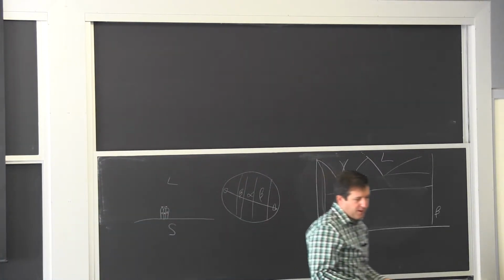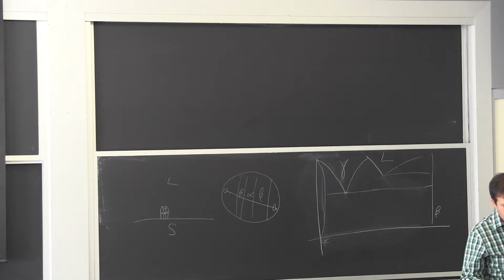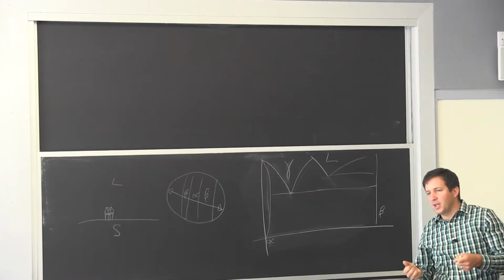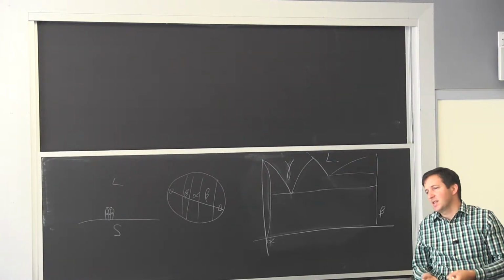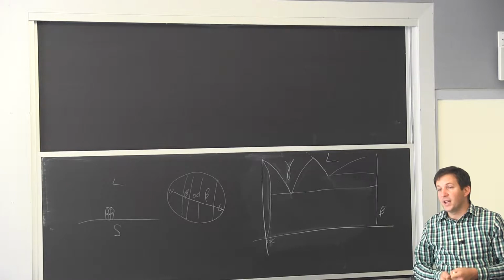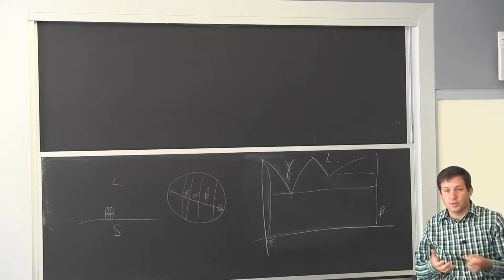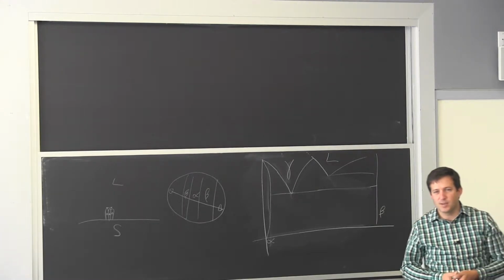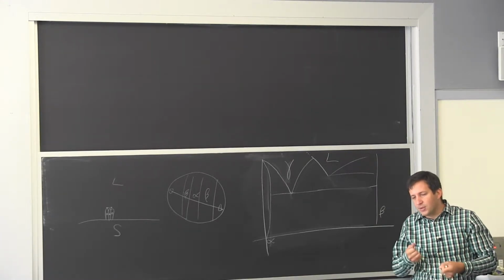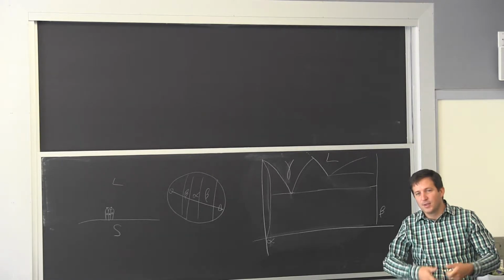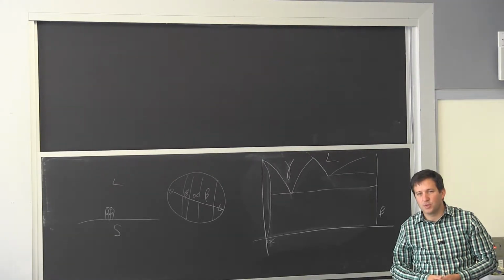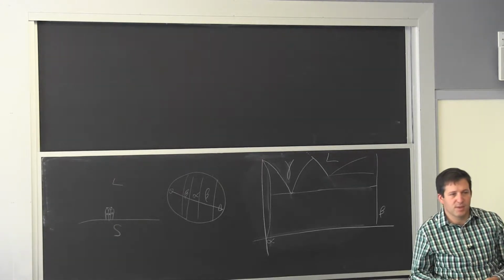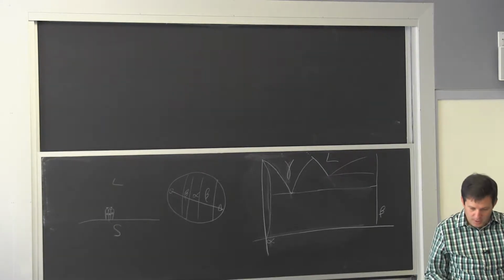So in effect, the steel is becoming a little bit like a viscous fluid. You keep deforming it, and it keeps resisting the same amount. If you try to go faster, it will get harder. So there is a certain similarity. It is solid, but the behavior is somewhat similar. You go faster, it gets harder, and you slow back down again, then it goes back to where it was. So it's a nice property in terms of having all these processes being in steady state, essentially.